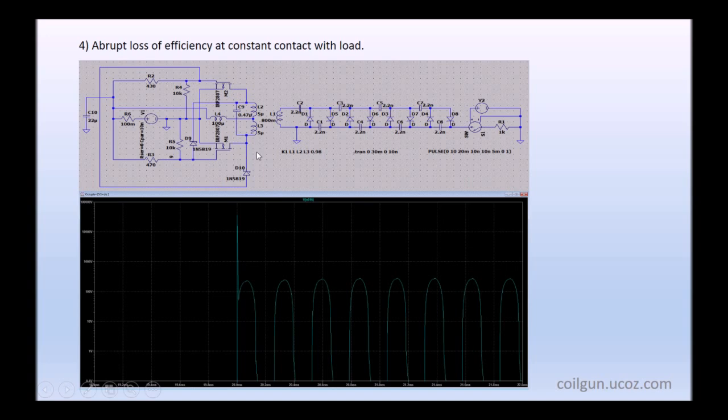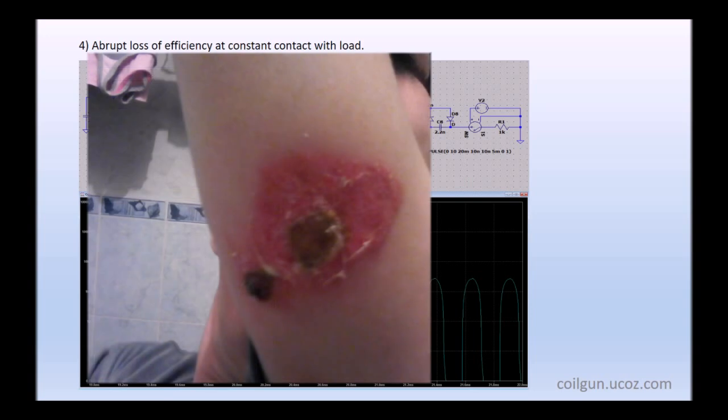It can also stop its generation in such conditions. It is not a rare case, but even if it generates, it produces high frequency pulses according to the ZVS resonance. It may be units or tens of kilohertz, and we saw in a previous part that such frequencies are inefficient.